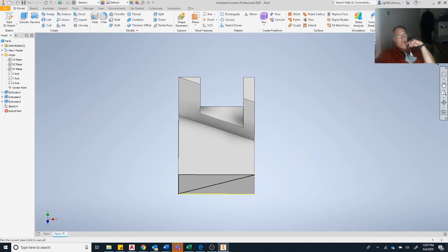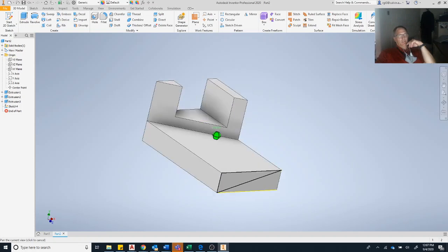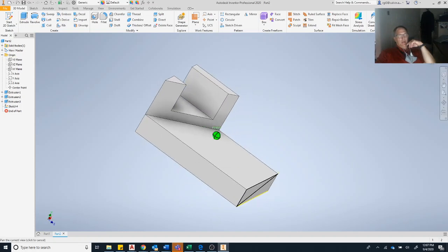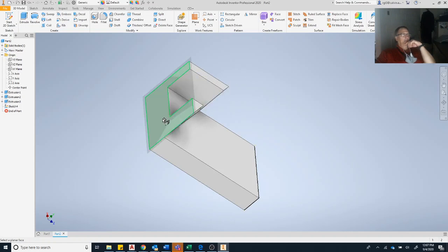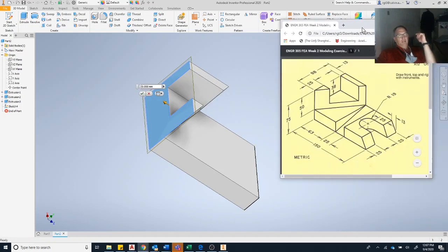Actually, I'm not going to grab it from the front face. And the reason for that is it takes more math. I know you guys are going, what? Yeah, it does. To get the distance from the front plane back, I have to do 150 minus 63 plus 25, or 150 minus 63 minus 25, however it is.